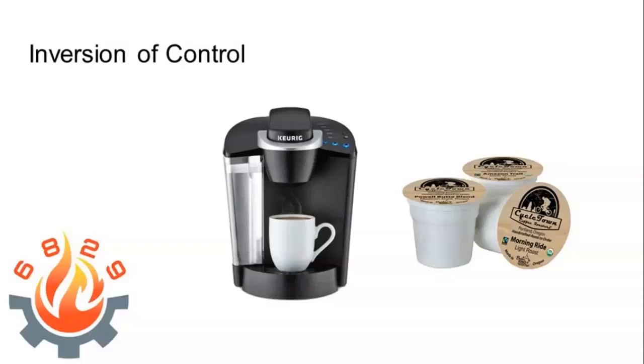As an example, would I collect my joystick inputs in the initialize method, actually run the arcade drive method and execute, and then call stop? No, don't do that, because if you read the joystick in initialize, it's going to read one time, and you're going to have that value the whole time, right? So every time you go through the loop, you want to read the joysticks, because they may be turning left or right, or they may be changing power at some point in time. So all that needs to be inside the execute.